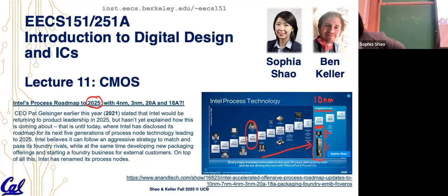Another very significant change, it'll be hard to tell here, is the metal stack over there. What they introduced is, does anyone know what they introduced? Intel introduced, for people who are playing with 18A? Adam? Backside power delivery. Yes, backside power delivery. What's that? Oh man, I don't totally understand it, but there's the layer that has the transistors, and there's metal and metal and metal, and inevitably the metal all gets congested. If you can put more metal on the other side, you can move power to stuff without taking up valuable routing. Exactly.